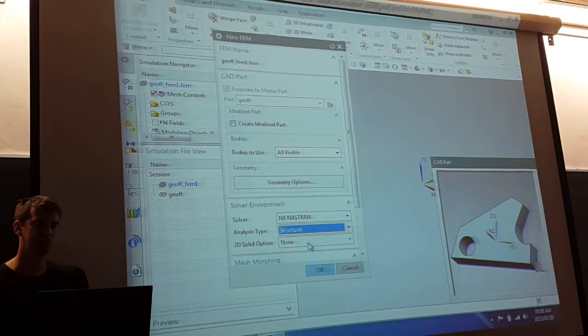We select it. We've got a few options here as far as the properties are concerned. I will talk a bit more about this in the coming weeks. But right now, the element type, the 10-noded CTETRA element, is acceptable. Mesh parameters, what element size are we using? This little lightning bolt icon next to the entry field allows you to implement automatic element size computation.